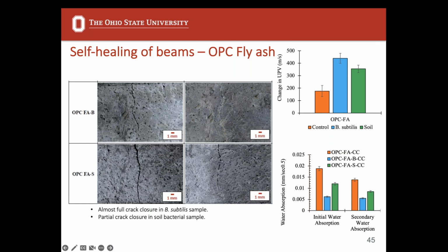So this is a sulfate mortar bar, a 1 inch by 1 inch by 11 inch mortar bar. And you can see almost the entire width of it here. So this is a 1 inch section we're showing the crack healing on. You can visibly see it with your eye in the lab. So it's not a microscope tracking thing.